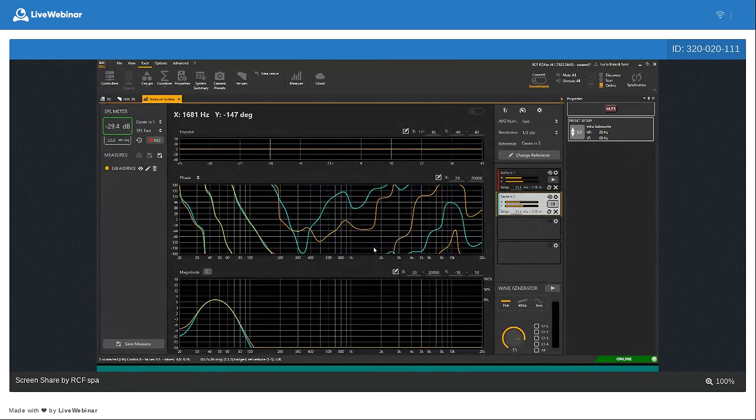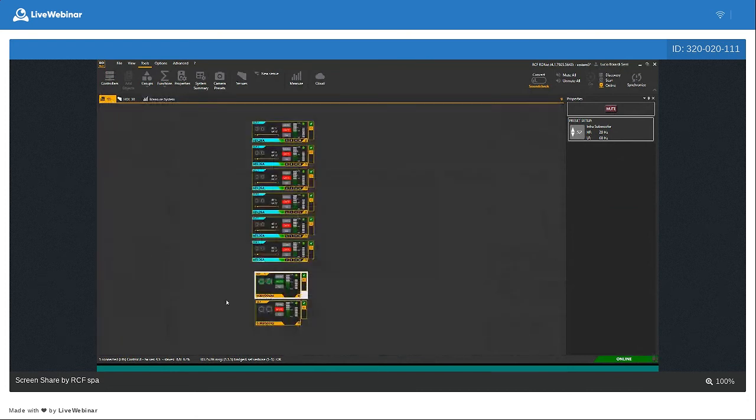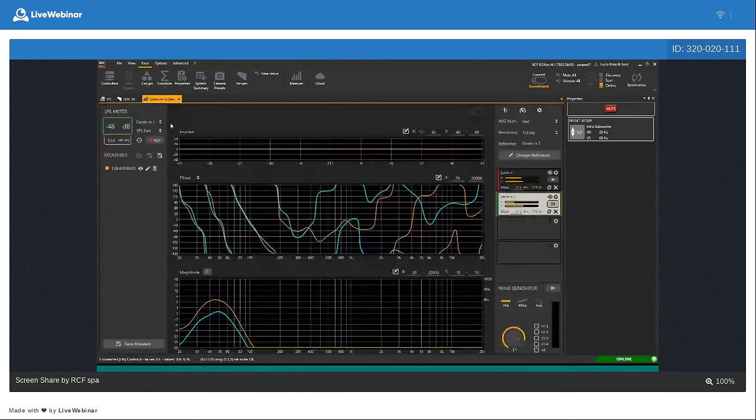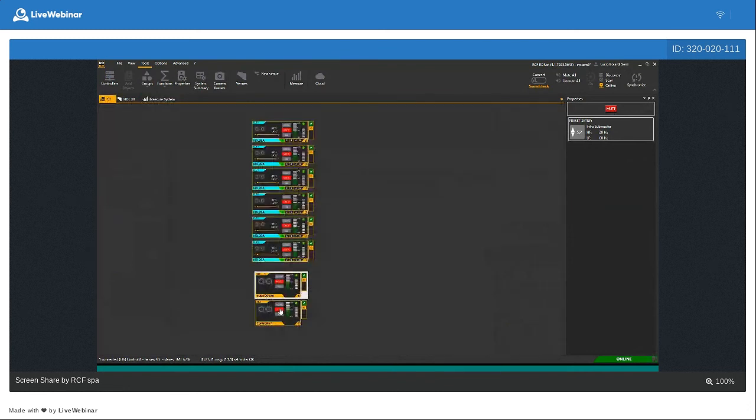As soon as I cancel this, automatically I will zoom the same sub in the audience, because now we are looking at the rear microphones. So go to our synoptic design, mute the subs because the measurement is there and also the phase is there, and unmute the other one, the subs that is facing backward.